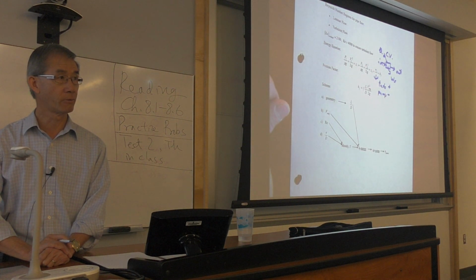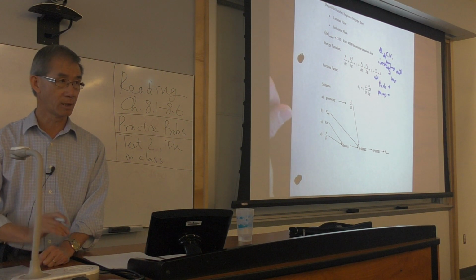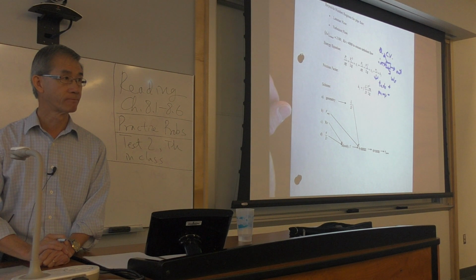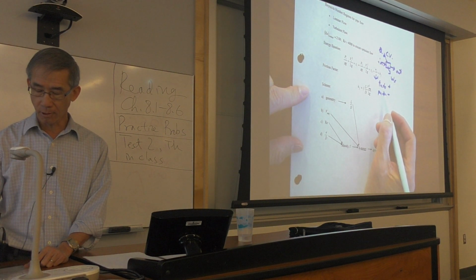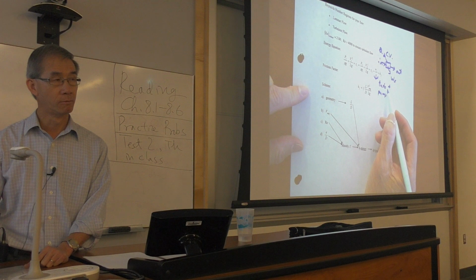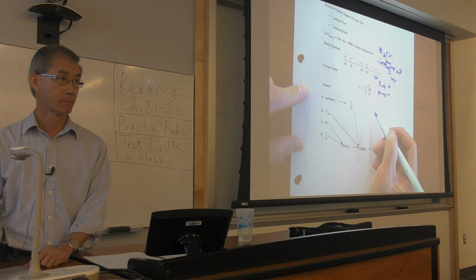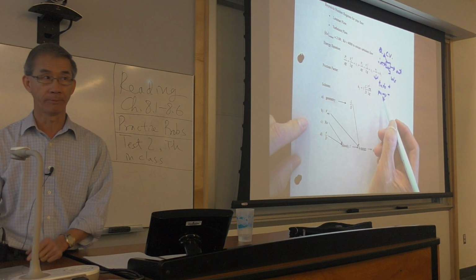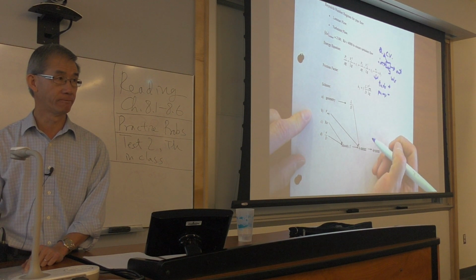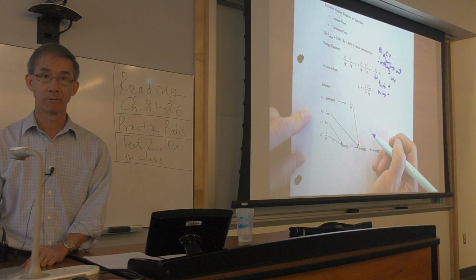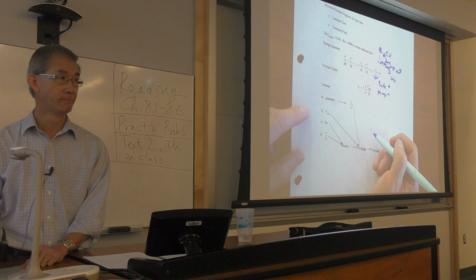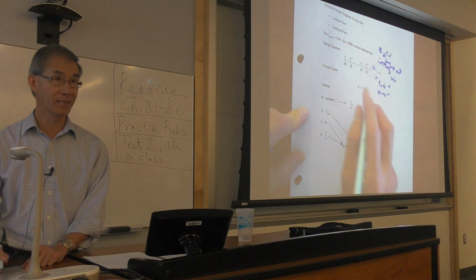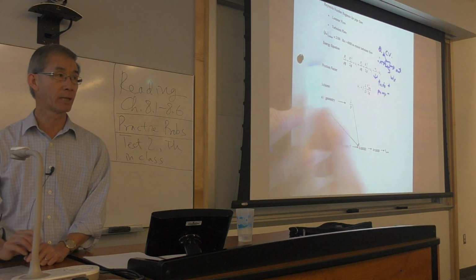You have seen this from thermal, right? That's a contract, something you sign on the dotted line, and we have to comply with it. Because of that, work done by the control volume, like a turbine, is positive. Contrary to that, work added to the fluid, like a pump or compressor, is considered negative. Do you get it now? And for the same reason, our contract says heat added is positive into my control volume.